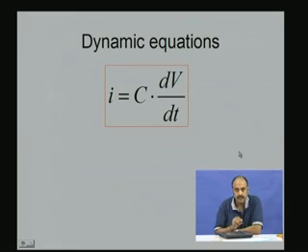The steady state equation is when everything is under stable operating conditions, nothing is varying, nothing is changing. In dynamic conditions, there are transients, there are step changes. So, these are the dynamic equations, which are the more general equations. Under steady state constraints, you will see the earlier steady state equations coming into play. In the case of the capacitor, the voltage across the capacitor is remembered by the capacitance. So, the voltage is the state value.